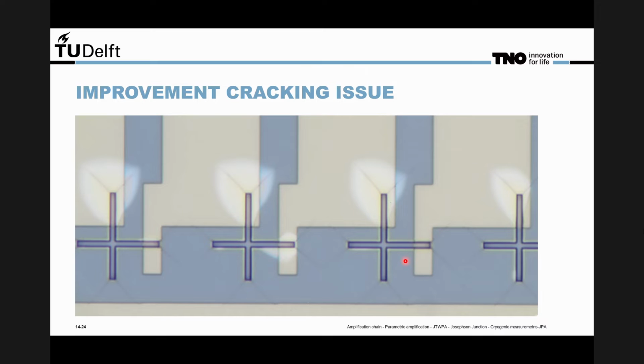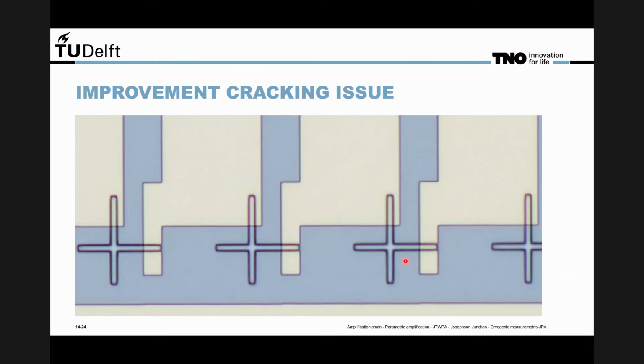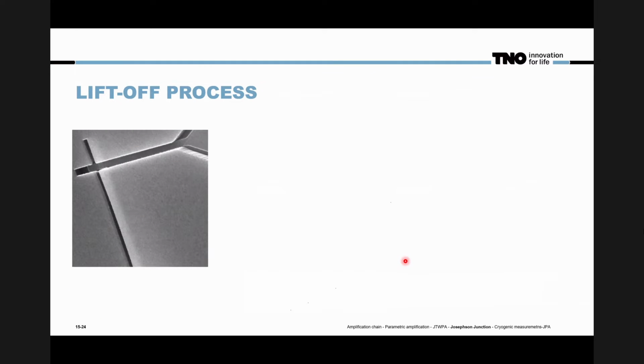So we found that by using a cold developer instead of a room temperature developer, we can get rid of these cracks. Then we get something like this. And preventing the crack formation was actually just one of the fabrication improvements I developed. But anyway, moving on to